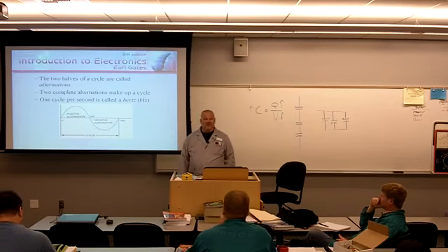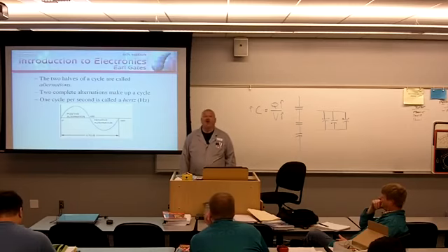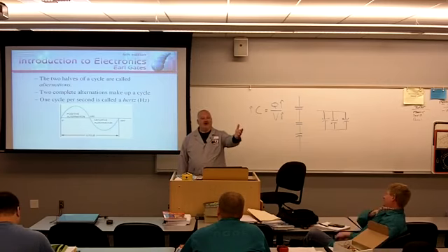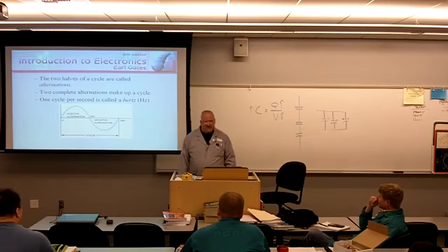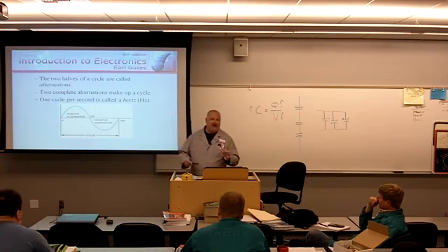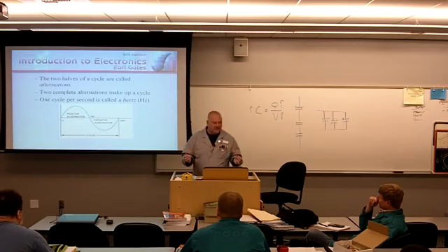Check this one out. You want to do something really funky? What is the sine of 270 degrees? -1. The calculator knows that we're operating during the negative alternation. If you plug in 270, it knows that it's the negative alternation. So for a lot of you that never had any use for trigonometric values on your calculator, check that out. Now you got that sine key. You could predict what is known as the instantaneous voltage present at any point of a sinusoidal waveform.